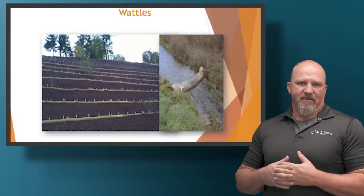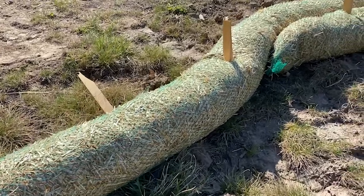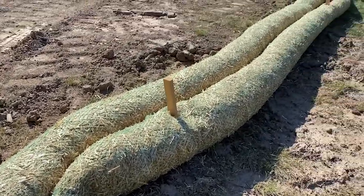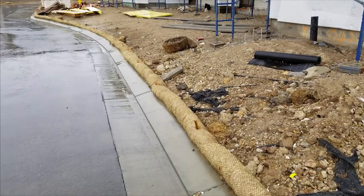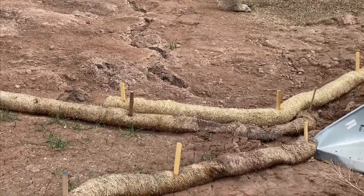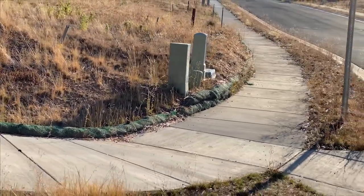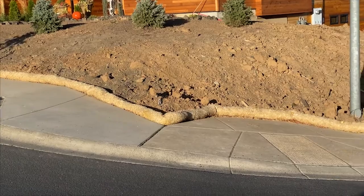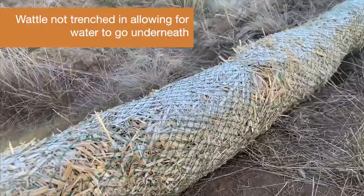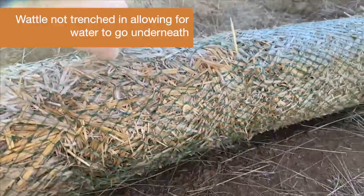Wattles are another perimeter control that are often used on projects. They're often used on projects where there's a lot of wind or potentially on projects where you want to leave the perimeter control in place and walk away from the project at the end. Wattles are often made out of straw, but there are all kinds of different wattles out there. They're mostly cylindrical products, and if you put a cylindrical product directly on the ground, there's often not a lot of surface area coming in contact with the ground, and water's going to go underneath.